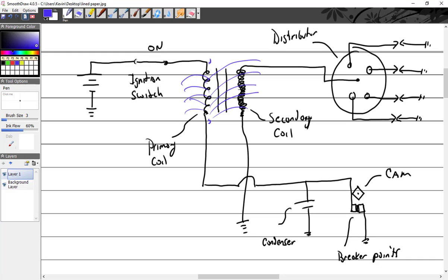Here are those coils cut away. So here's the secondary and here's the primary. Actually, I think this is half of the secondary. It looks like there's all secondary split in half. But you can see that inside there, the primary has a lot of turns of heavy wire, and then the secondary has fine wire. How many? A lot more. About 200 times? 200 times, about. So we have the soft iron core about 20,000 times.